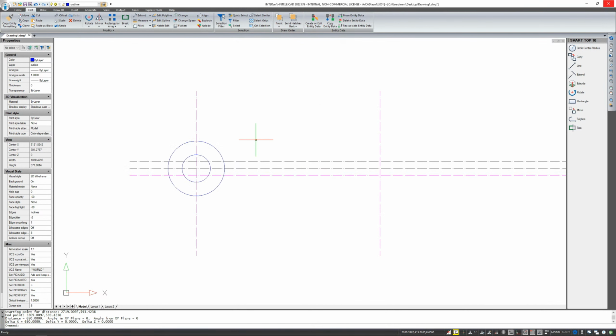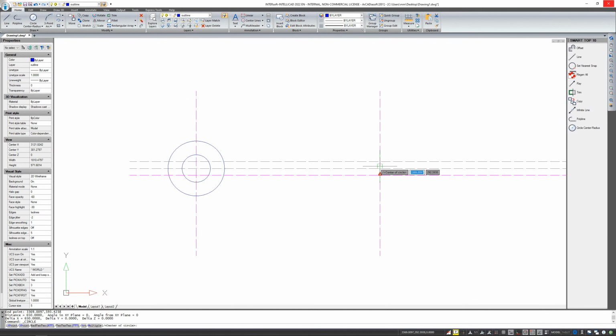To sum up, copying and moving is similar. Either you select an element and copy it, or you simply move it, only then you move with a specific point or with a displacement. But then you select the displacement either in the command area or under the mouse cursor. I'm going to draw one more circle here, which will have a radius of, let's say, 100. And now I can draw more circles in the same way as this circle.